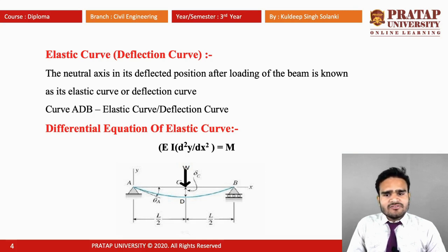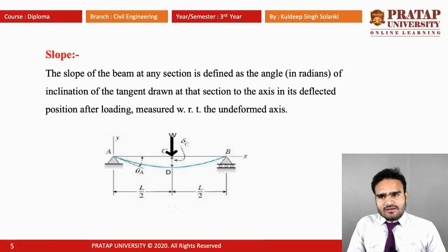And the differential equation for the elastic curve is EI d square y upon dx square equals M. This equation is for the deflection curve. Here E is the modulus of elasticity, I is the moment of inertia, and M is the bending moment due to external loading.